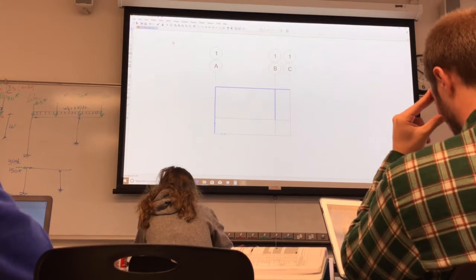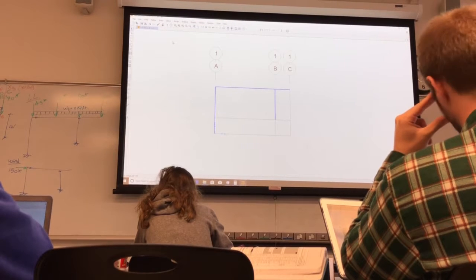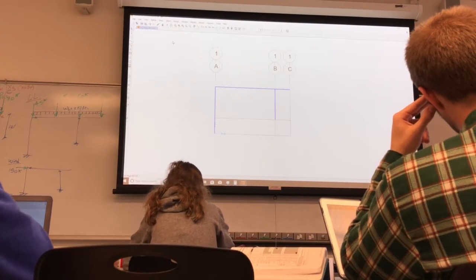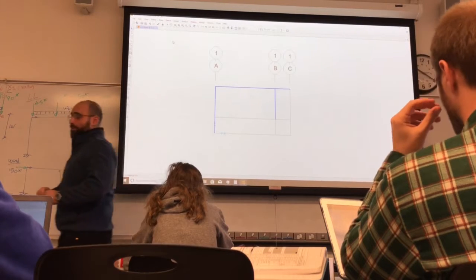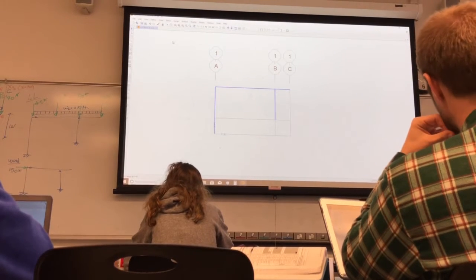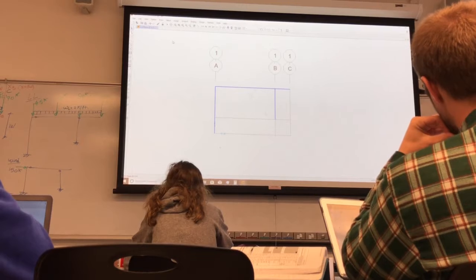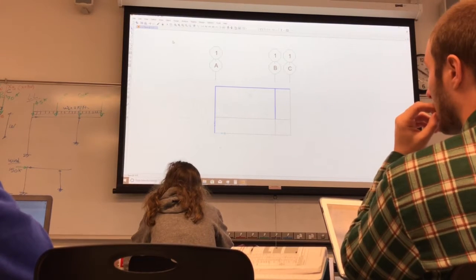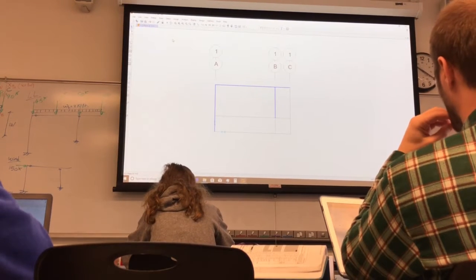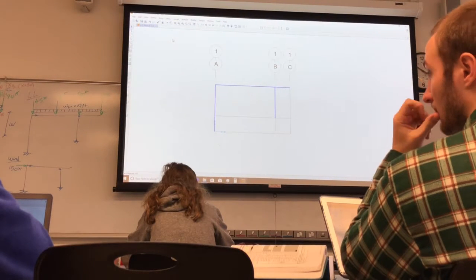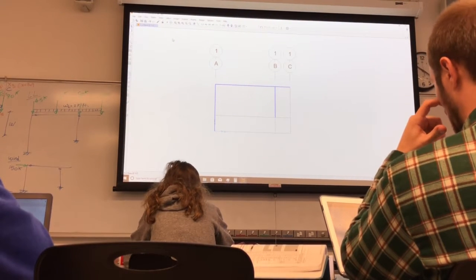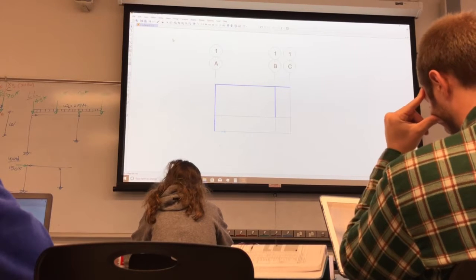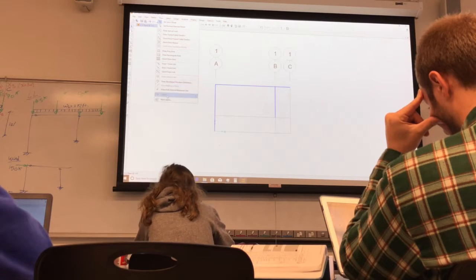So you're going to define the distributed load for both sections? Yeah, we have to. We'll see that in a few minutes. That's why I said you need a node at each point, at each intersection. That's why I put a node here. I can't just have one beam, because it's not going to see that the column and beam are connected together. So that's an important question. That's the frame, how it looks, and there's nothing else we need to draw. So we're done with this.